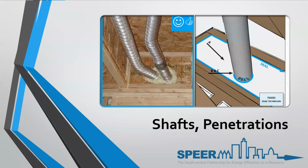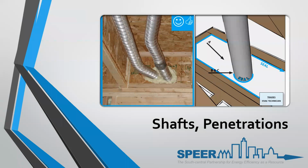So that's a lot of wording there just to say you need to make sure it's air sealed, and then you need to push insulation as close as you can to what's penetrating through that, within means of, if it's a flue pipe or some kind of combustible piping that's there, you can't have combustibles in touch with it. We'll see that next, I think, maybe not on the next slide, but these shafts need to be sealed.